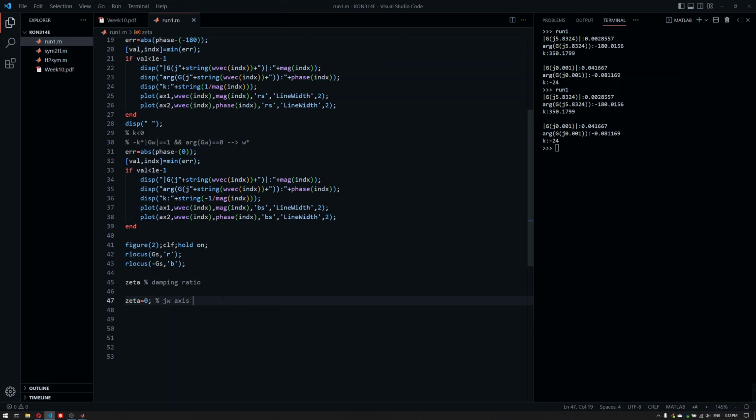And this zeta value is going to be between 0 and 1 or greater than 1 or exactly 1. We don't quite know that. For second-order systems, since zeta is only defined for second-order systems, there should be a relation between zeta and our frequency or point where we pick this value.